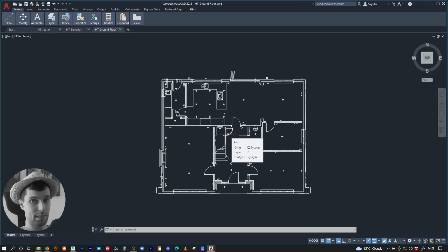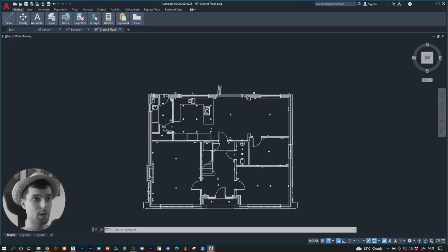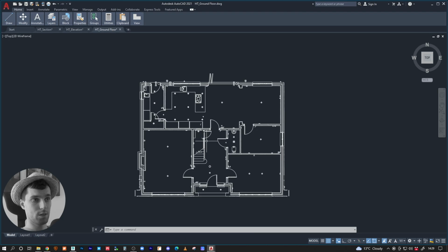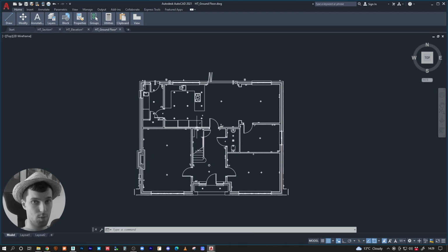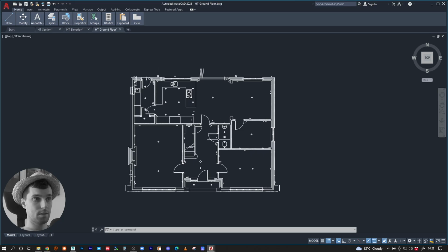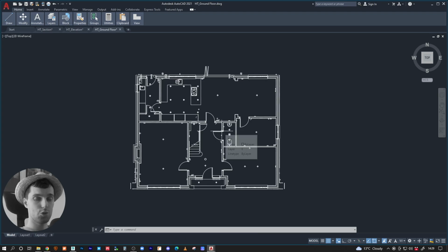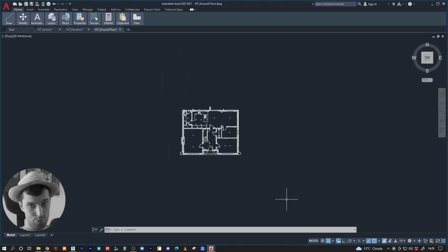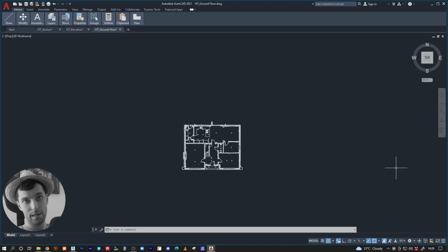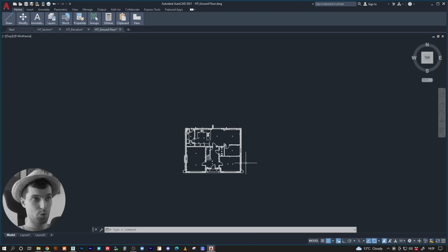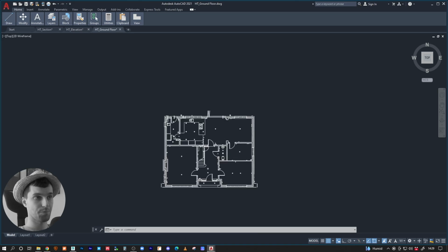It's not really a big deal if you screw up here. But literally what we did now is we cleaned the drawing as best as possible for what it is. And it's light enough, and we can now export it as a DWG, right? So we cleaned the drawing, we purged, we exploded it, we moved to a 0 layer. We did delete everything around the drawing, so we don't really have any other garbage around the drawing, right? We're only concentrating on this drawing, okay?